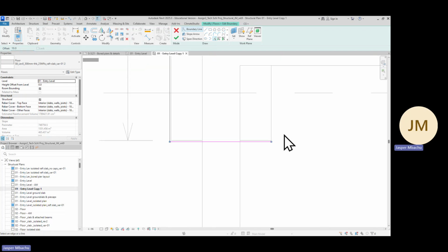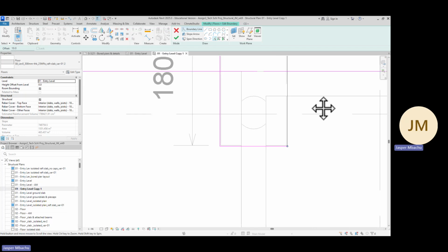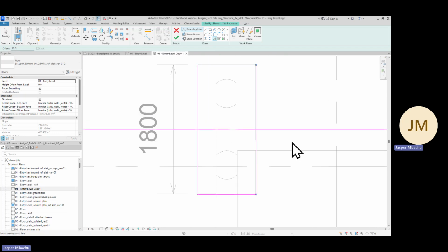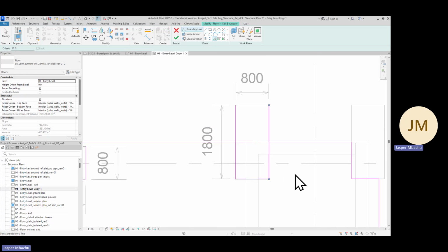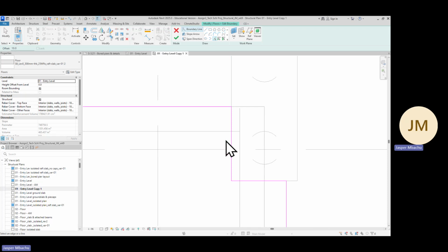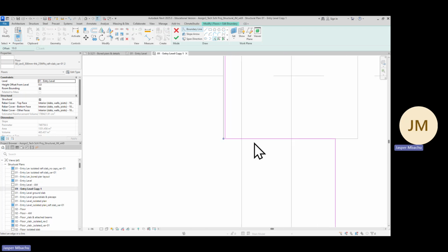And here too, I'll take it to the right side, so the dotted line is to the right, so you click. So I have a 10 mil offset all around it. I'll click. It might actually go ahead and provide one, because I didn't do it here, so I might do that as well.